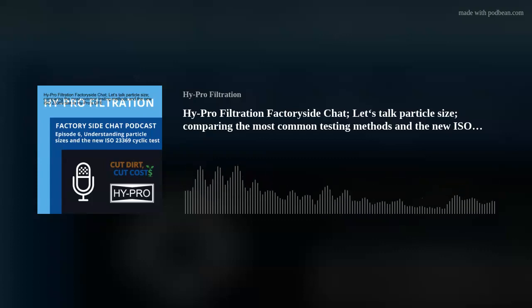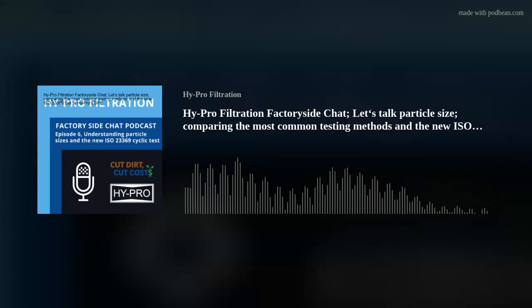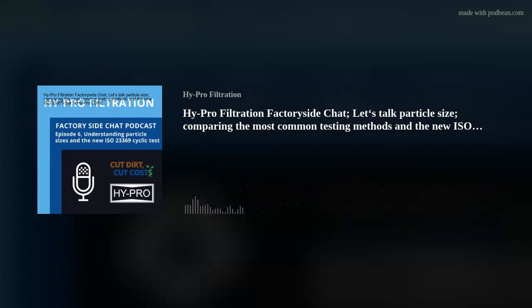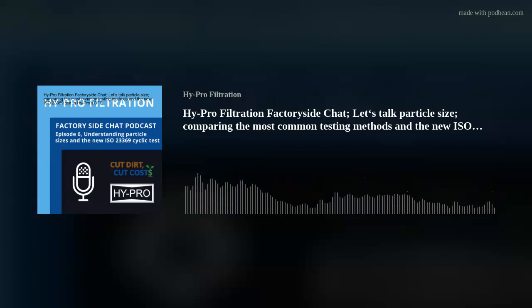Yeah, so if you see ISO codes that are either the same digit across all 3 codes, or maybe the 4 and the 6 channel are showing the same codes, then you look at the individual particle counts and they're all very close together and most of the channels are very high. That's a really good indication that you have either air, water, sometimes even varnish in the fluid. Okay. All right. That's good.